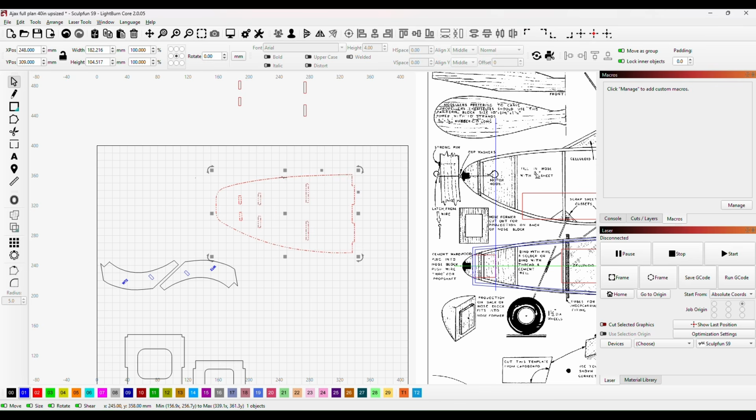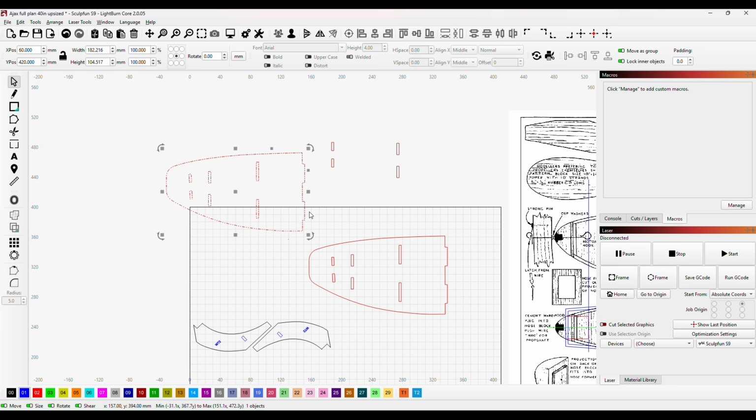So what I'm going to do is copy our size sheet for the nose, and then ungroup just this one, and then select our slots that mount the nose mounting, and all I'm going to do is press Control and Shift, and take this 1 millimeter towards the rear.